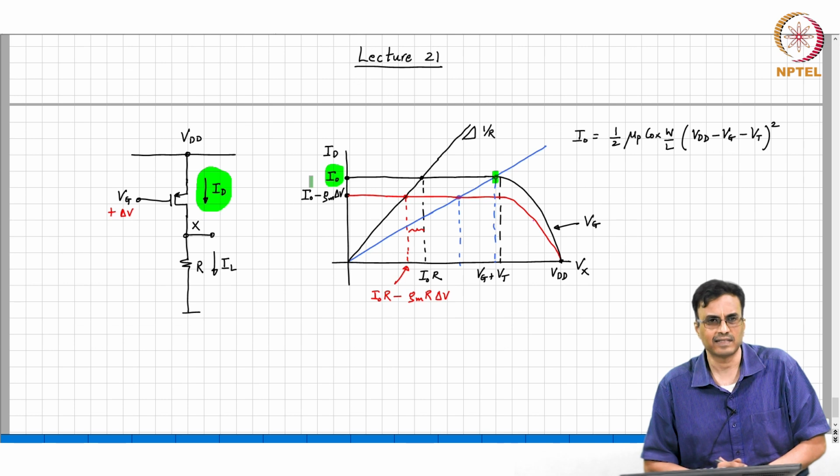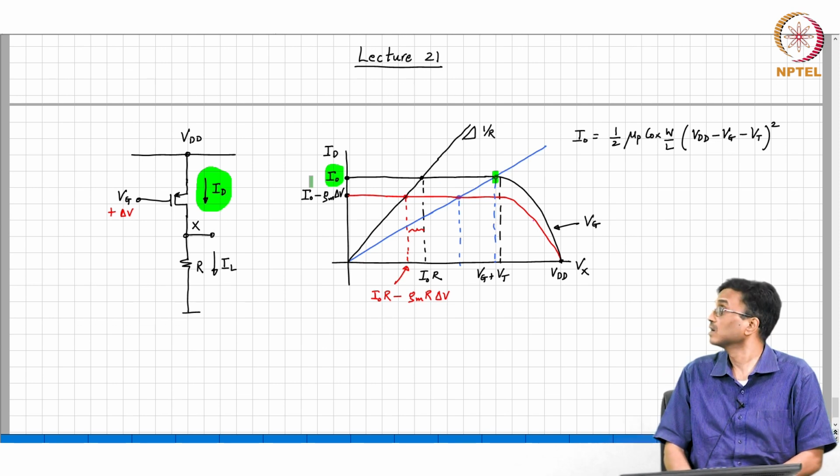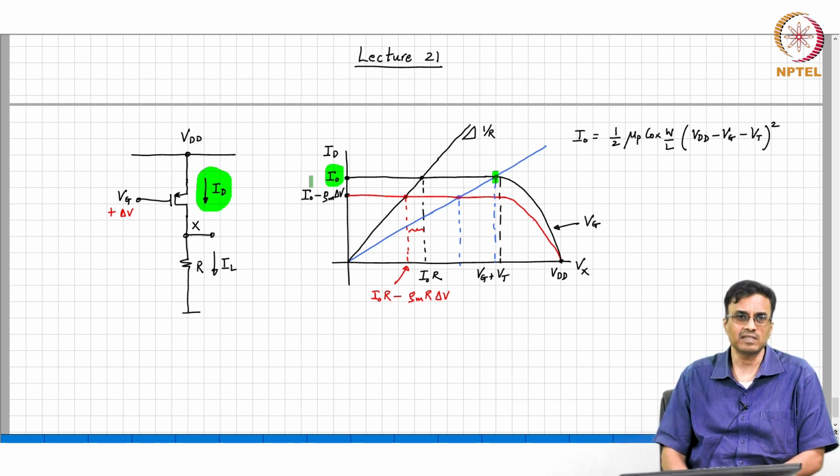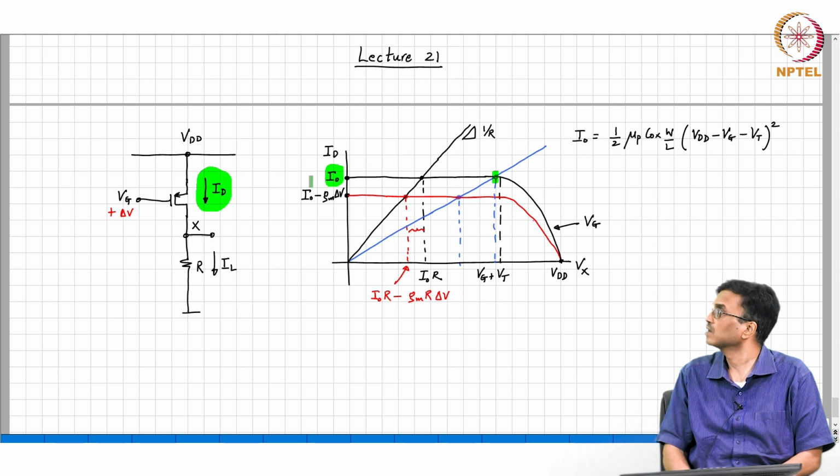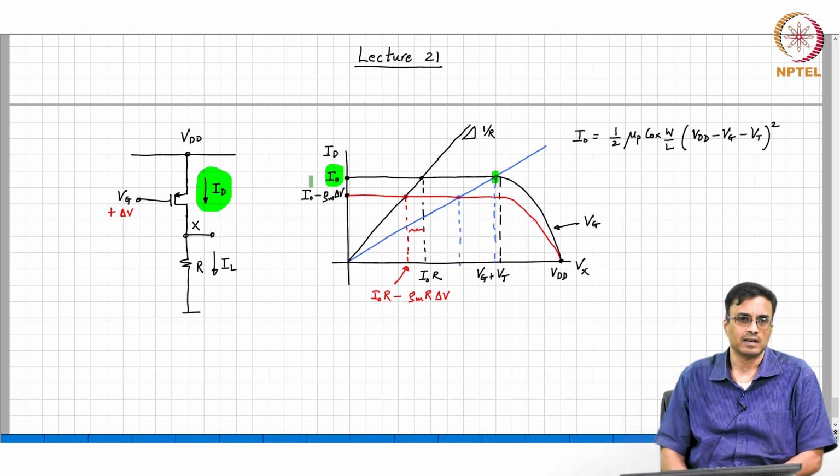The transistor is the same, the quiescent current is the same, so the gm is the same, so that is not a choice. What can you do to this circuit so that the incremental gain can be increased beyond what we have right now, which is assumed to be the blue curve?